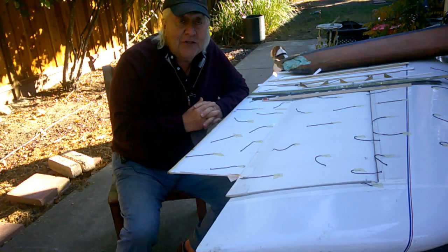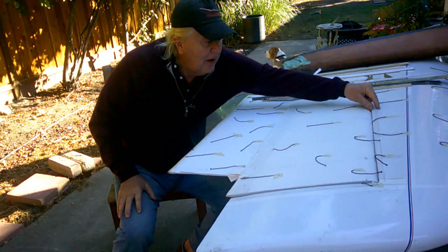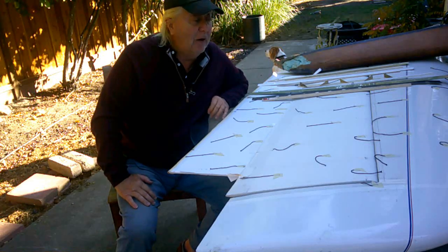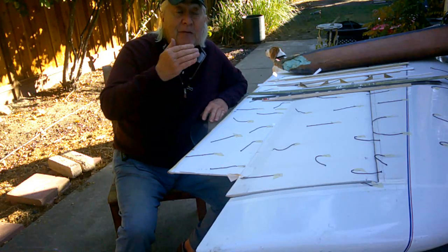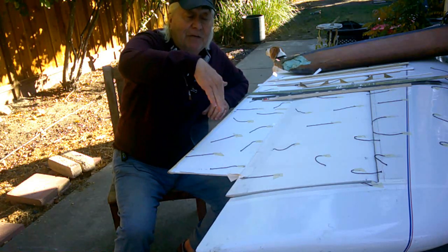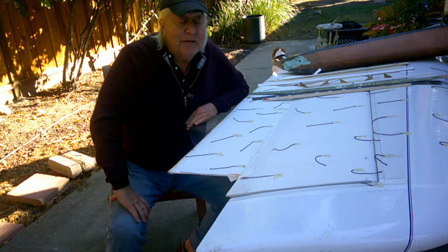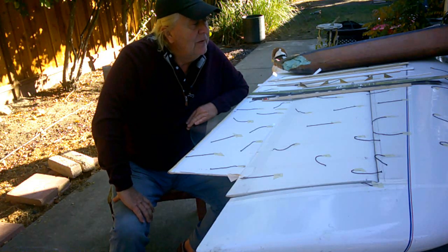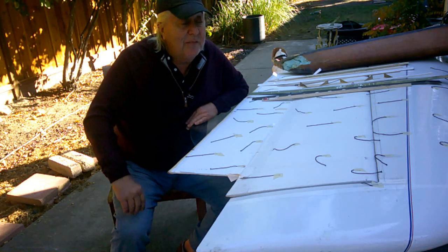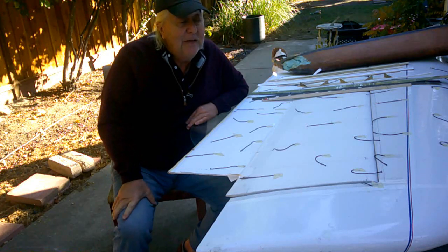Now, we did try vortex generators here early on and placed them just in front of where the elevon hinge line is, and it didn't help at all. We thought we'd be able to energize the flow before it has to go around the corner when the elevon's deflected down, and it didn't work. So I thought, well, maybe it's not a Reynolds number problem, and this wing is essentially the same as my first wing. I don't see why I have a problem.